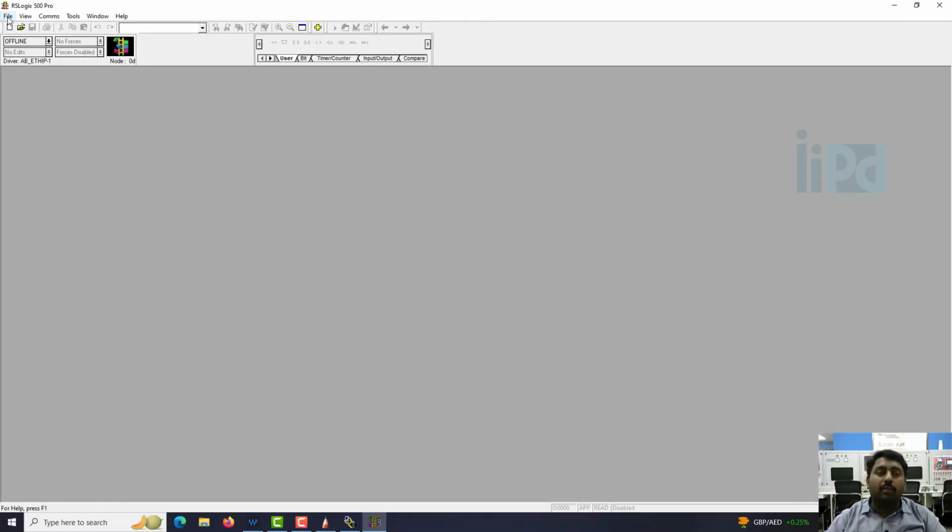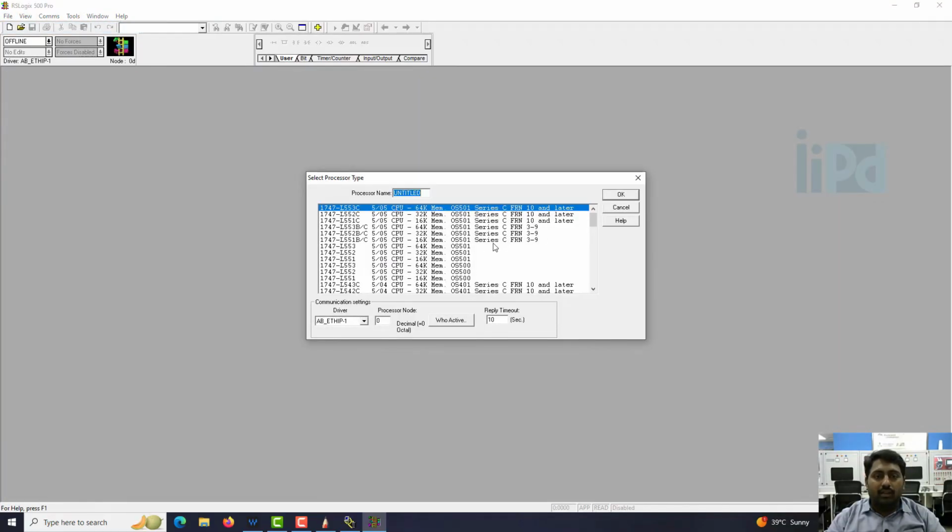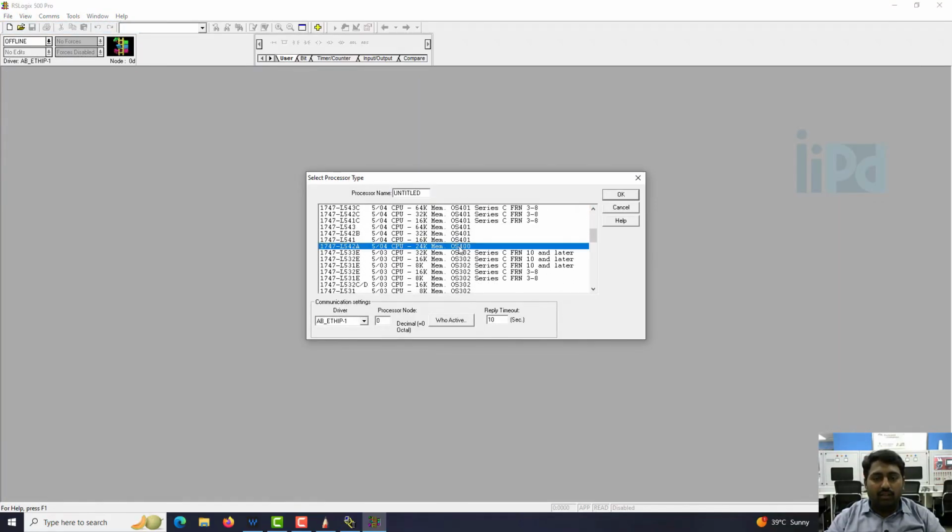It will read from a server, and after that, in the next video, we will see the PLC acting as a TCP server. TCP client is basically the Modbus master in TCP, and TCP server means the Modbus slave. In RS485 networks it is called master-slave communication, but in Modbus TCP it is called client-server communication. Okay, so let's create a new file.